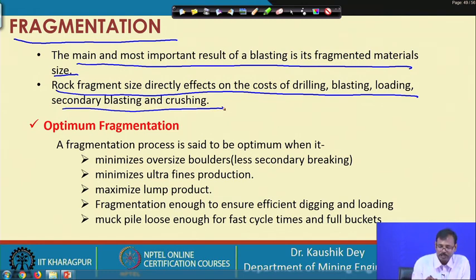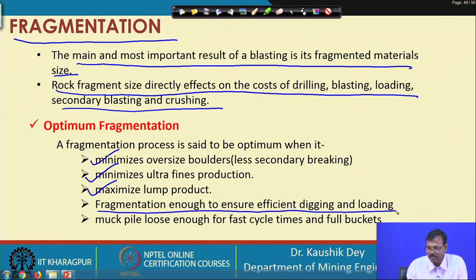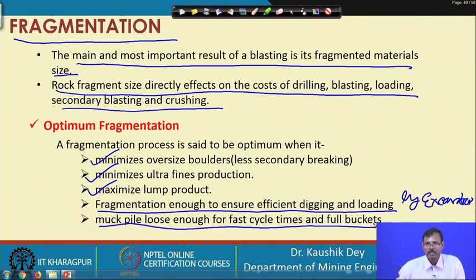A fragmentation process is said to be optimum when oversized boulders are minimum, ultra fine production is minimum, lump sizes are maximum, and fragmentation is enough to ensure efficient digging and loading by the excavating machine, and the muck pile must be loose enough so that the bucket can be filled very fast, and very good shovel performance can be achieved.